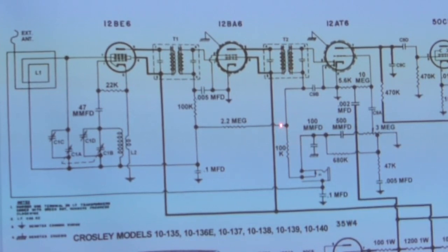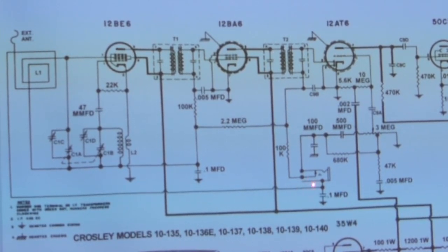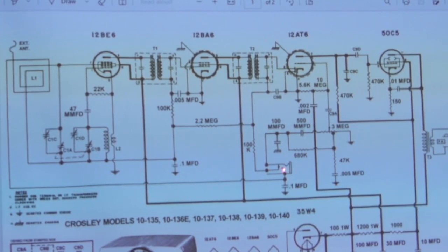All right, so we're down here, and we said there was an audio split off, and here it is at this point. Then it comes down. This is shorted out because this is a phono input. This disconnects this portion of the circuit when you plug in a phono input, like a record player or something, and then it goes straight into the audio portion. But otherwise, through the internal connection on the plug itself, this is connected audio-wise through here. You'll notice there's one more RF filter there, just to make sure you've gotten rid of all of your RF component coming down here.